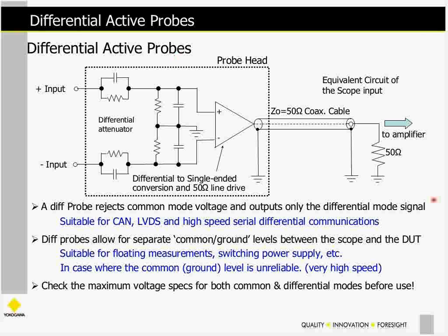And so these are also used for serial communications or logic. We market some that are designed to work in the range of 20 volts, and we market some differential probes that are rated for around 7 kilovolts as well. And notice that my differential amplifier here does not have any symbol for isolation. There's no galvanic isolation here. So this is not an isolated probe, nor is it an isolated amplifier. And isolation usually is something that you consider when you need to keep your measurements from affecting one another, and also in terms of safety.